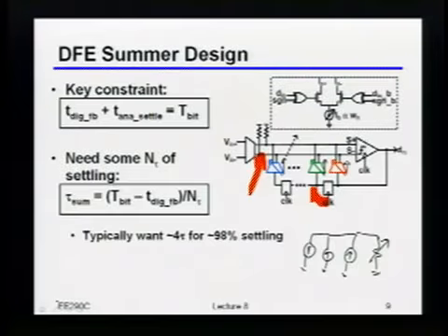Not from the GM, just from the fact that, as an example, remember there's some data pattern in the shift register here, right? So let's say I had 20 taps. It could be that I have 19 ones and 1 zero, and then that one zero I flip from being a 0 to a 1, right? The voltage impact of that would be very different than having 19 zeros and flipping the last tap from a 0 to a 1. That's the nonlinearity I'm referring to.